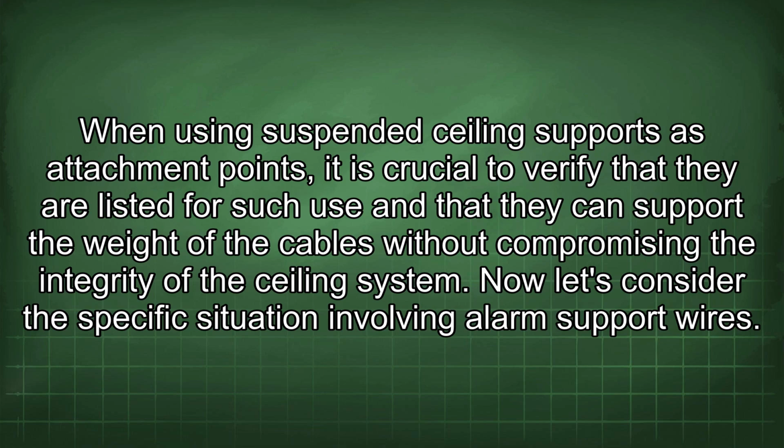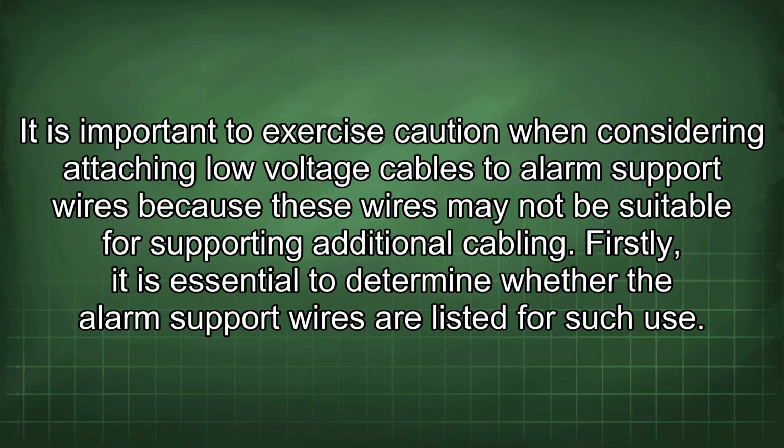Now let's consider the specific situation involving alarm support wires. It is important to exercise caution when considering attaching low-voltage cables to alarm support wires because these wires may not be suitable for supporting additional cabling. Firstly, it is essential to determine whether the alarm support wires are listed for such use.